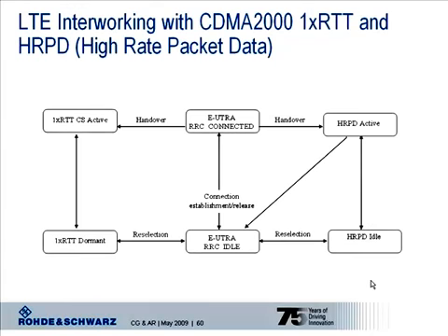Of course, not only is transition from LTE to GSM and wideband CDMA HSPA required, but also between LTE and CDMA2000 based technologies. This is true for both HRPD, high rate packet data, and for 1xRTT circuit switched services. And this figure again shows the allowed state transitions between RRC connected and the CDMA states, and RRC idle and the CDMA states.